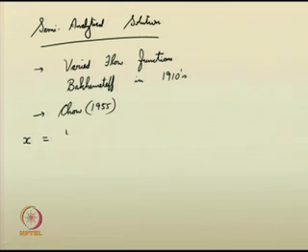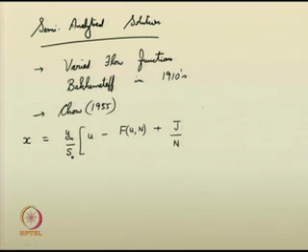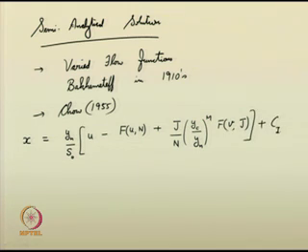So, one such solution is: your horizontal distance x is equal to y n by S naught into u minus the varied flow function f of u and hydraulic exponent n, plus a parameter j divided by n into y c by y n raised to m into the varied flow function of a variable v and parameter j, plus constant of integration C n, where u is your normalized depth y by y n, and j is a parameter obtained as n by n minus m plus 1.